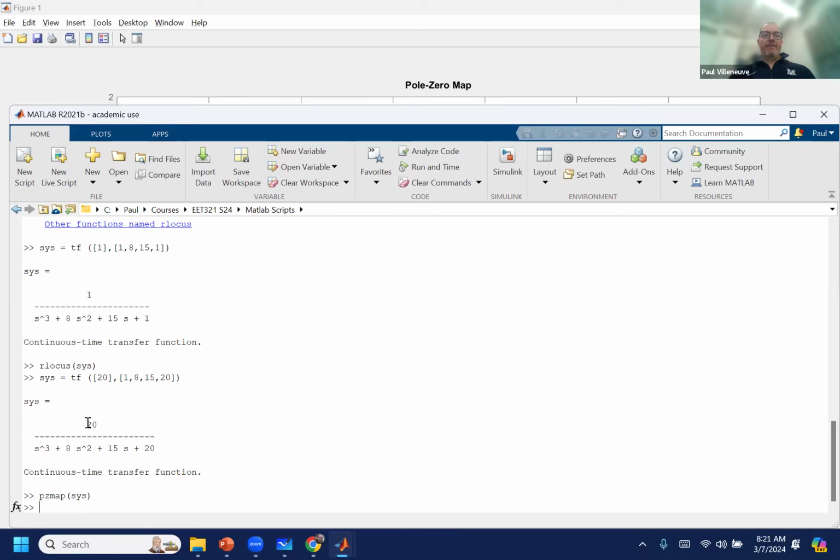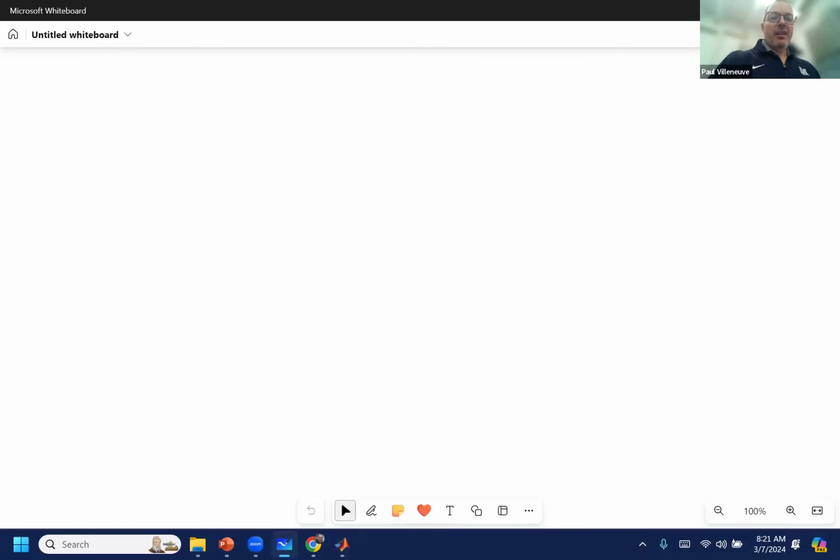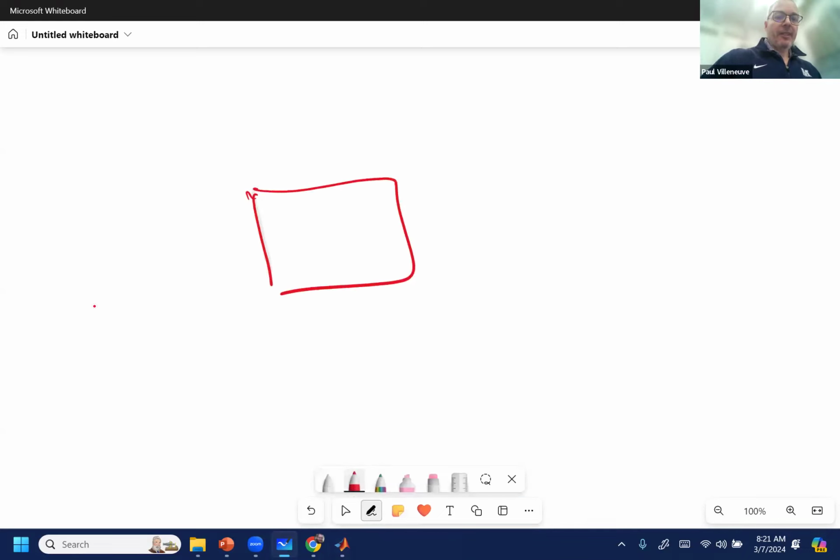Then why did you put the number? You substitute 1 for K, it's not one. Nope. This is just the base transfer function. So basically what I'm doing is I'm factoring K out, and then I'm keeping it as a gain. So my open loop transfer function, whatever you gave me, was 1 over s cubed plus and so on.